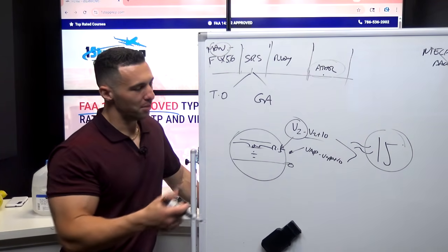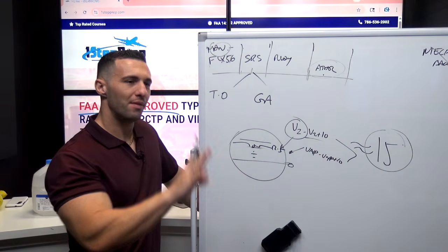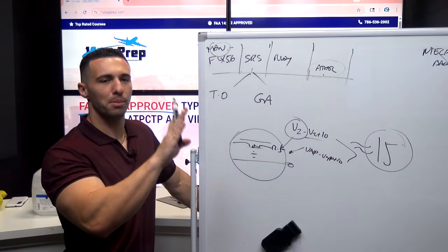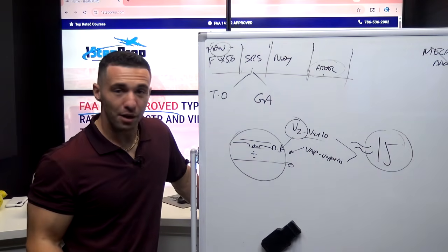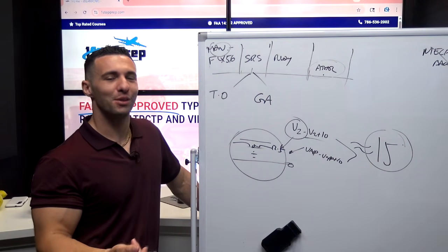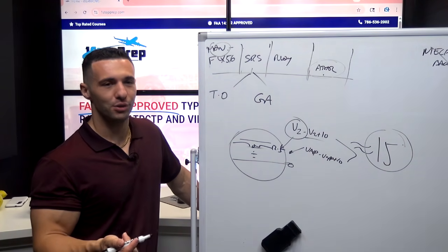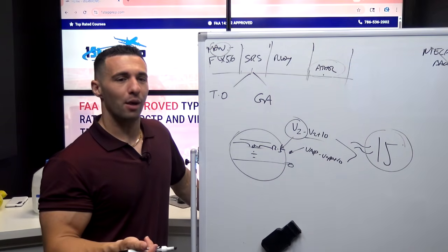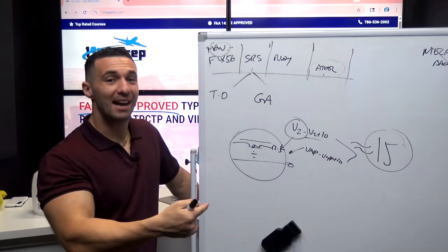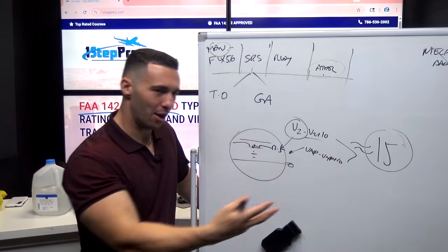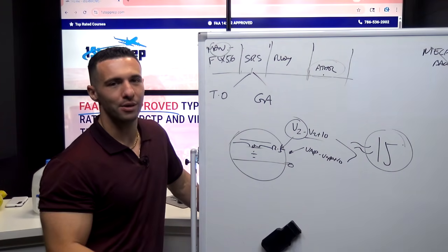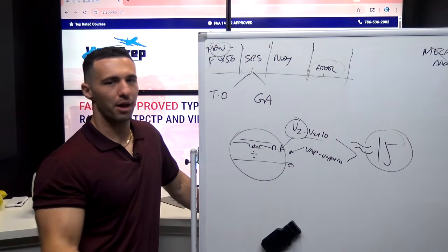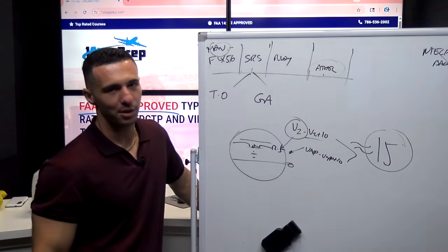So in terms of, when we're rotating and you have that over rotation, that's why it's pitching you up a bit aggressively, because it's trying to get you back inside of a speed window. Then, of course, you probably reached the thrust reduction acceleration altitude already, at which point the flight director bar now goes to 10 degrees to begin speeding up so you can begin cleaning up the airplane. So now all of this is out the window and we go into climb mode, and we're no longer in SRS anyways to begin with.